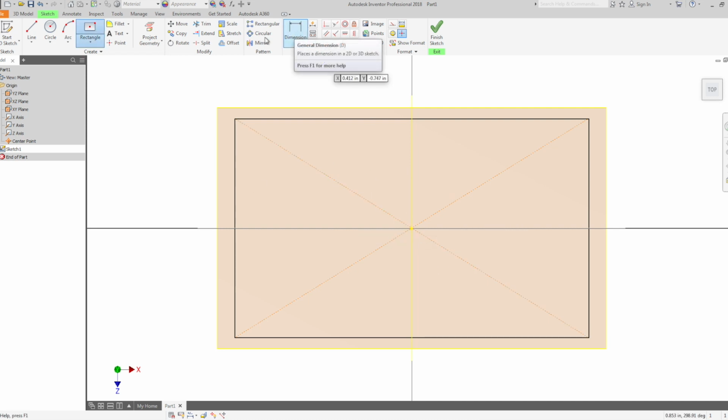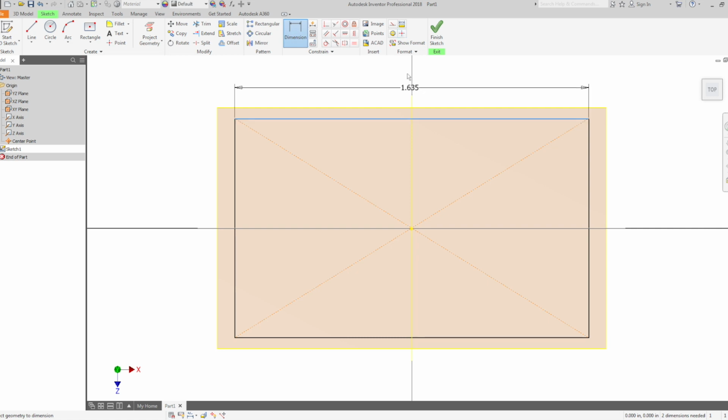We're going to go back in and put in dimensions now to make it the dimensions that we measured earlier. So I'm just going to click the dimension command up here. Click on the top line of this rectangle, and I'm just going to left click and release. And then I basically have this dimension that's kind of in space, and I'm going to left click and release again to place it. And now it's giving me the option to enter the dimension, which I'm going to type in, and we measured 15.5 inches.